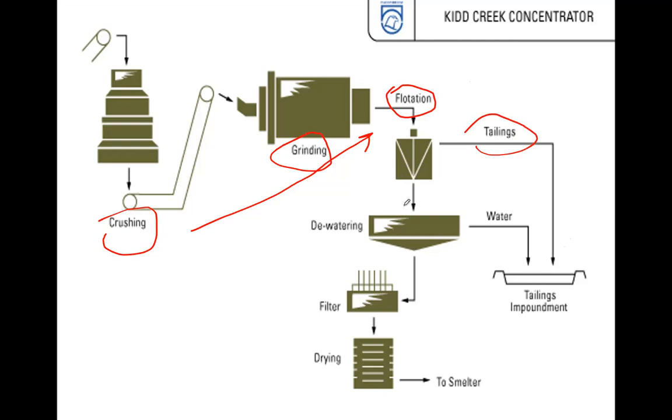And then you have to do dewatering, or if heavy liquid is used, heavy liquid means high density liquids are also used for separation, right? For example, if it is a zircon monazite like thing, you have to use a heavy liquid, because water cannot be used, because everything sinks in water.